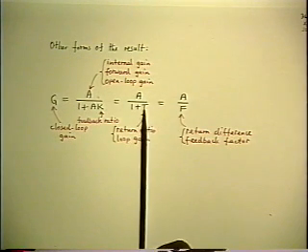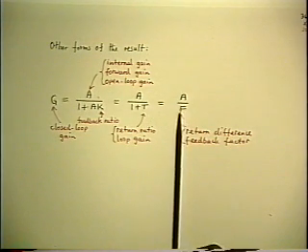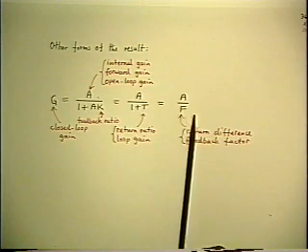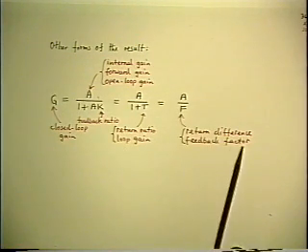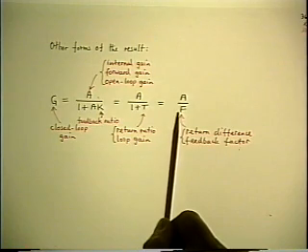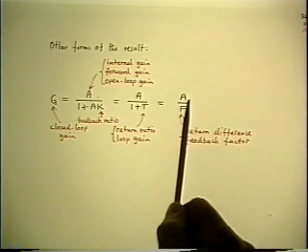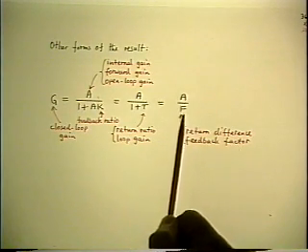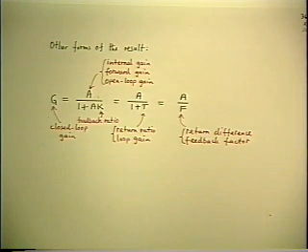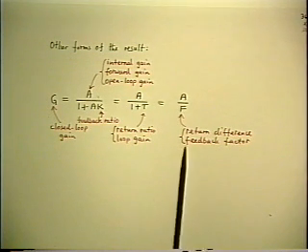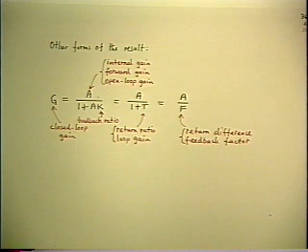1 plus T comes up so often that it also has a symbol of its own. F, I like to call it the feedback factor, because it's the factor by which the open loop gain is reduced in order to give you the closed loop gain. In other words, it's a measure of how much feedback you have.